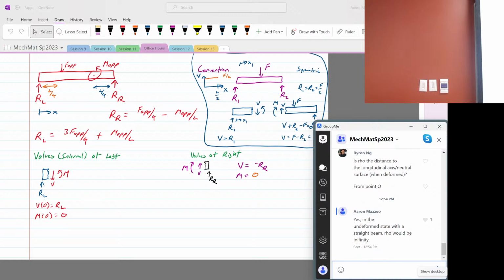This is pretty characteristic for steel, which has a shear modulus around 79 gigapascals or something. So put in 200 gigapascals and maybe 0.3, and it should be pretty close. That looks pretty good.